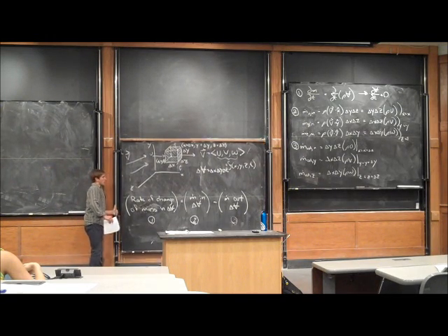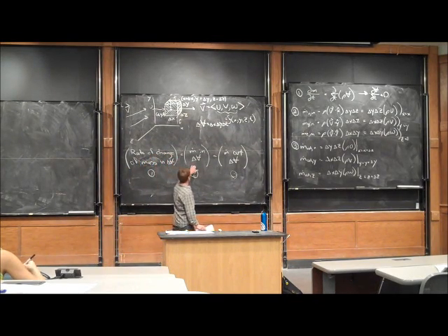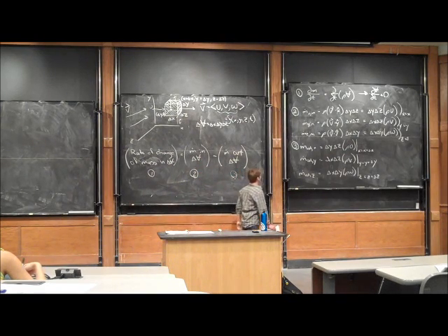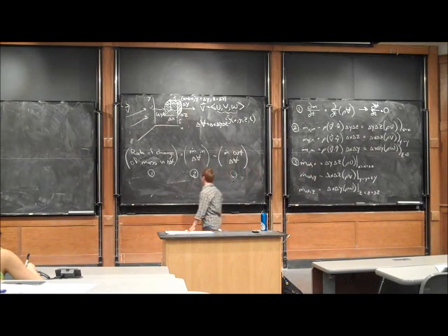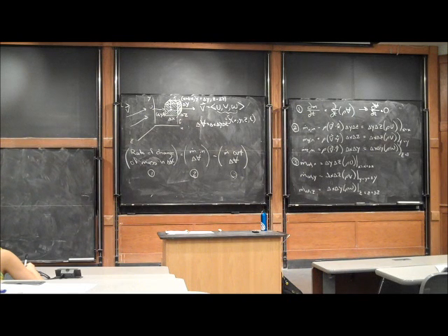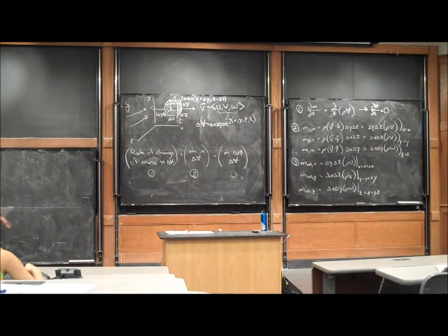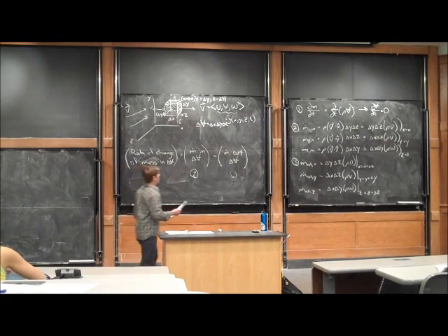So we have this global equation that we're trying to set up right here. We have the change of mass in our control volume is equal to the mass coming into the control volume minus the mass coming out of the control volume. We have then solved for all three portions of that equation separately so that it's easier to break apart, easier to see. So we can now combine all these equations and look at them individually. And if we look at that one side at a time, we have the rate of change of mass in the control volume, which is going to be